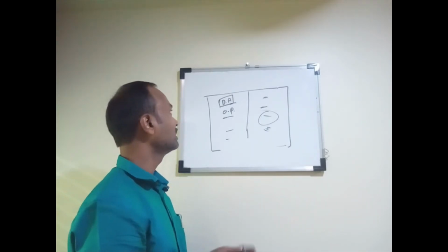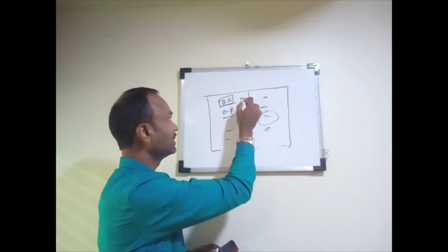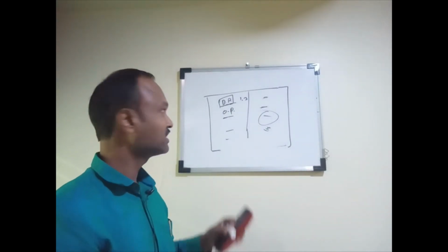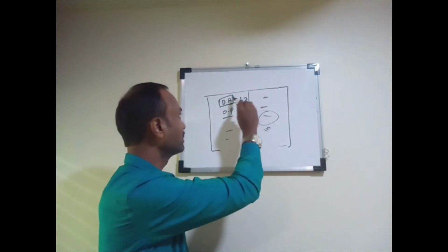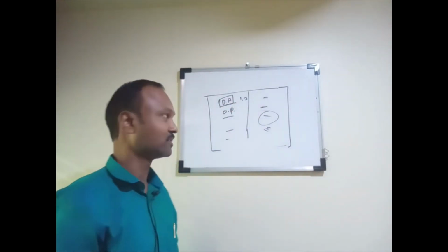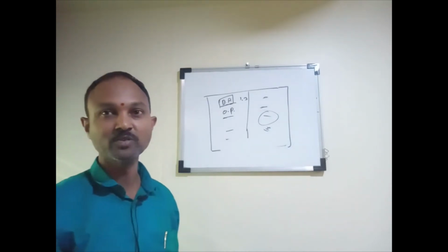That one is normally higher than this design pressure. Normally it goes to 1.3 times of this design pressure. So when you test with this test pressure, it will easily withstand the design pressure. So this is the second point we observed.